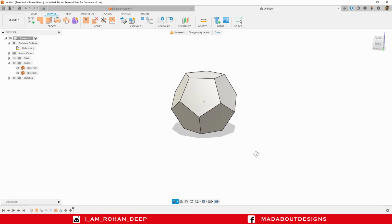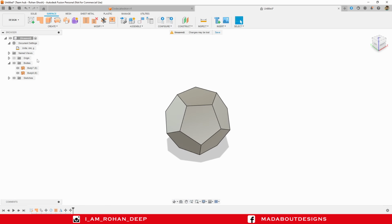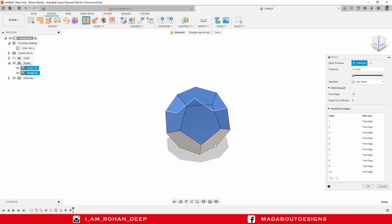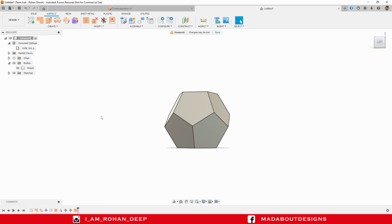Here is our dodecahedron ready. Now, as you can see, we have 2 different bodies. We have not joined them. To do so, under modify, click on the stitch command. Select both of the bodies. Here you can see where the stitches will be applied and click OK. Now you can see here all the surfaces have been transformed into a body.